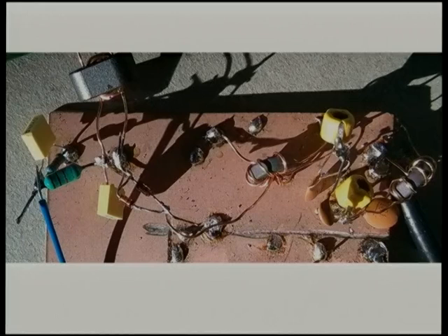This is the bandpass filter up here. These diodes here do the mixing. This other coil is where the local oscillator gets injected from the microcontroller, and this little wire here is the input to the analog digital converter. So that's potentially enough to receive a signal off the HF radio spectrum. We shall see.